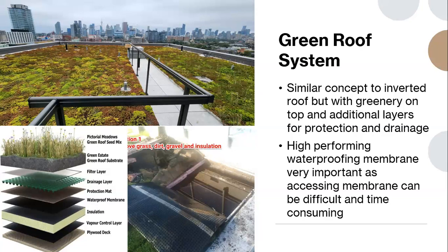Yeah, it's a great question. There's actually two sides to that answer. The first side would be maintaining the actual roof system, which, for the green roof, is just like an inverted roof system. So it has all the similar components. The most important things are making sure your penetrations are sealed and your drains are clear. The other side is maintaining the landscaping on there, which you would use a landscaping company for if the greenery does grow. You need somebody that understands how to maintain greens, and then they also have the roof system component. So two different specialties are required.